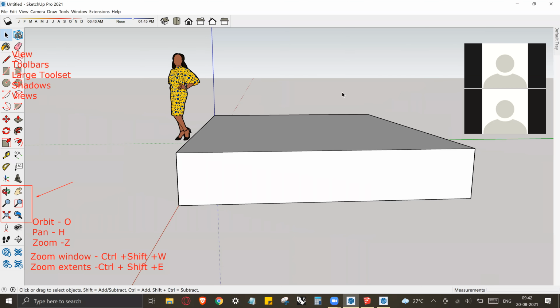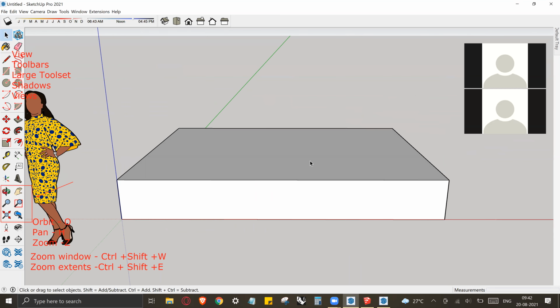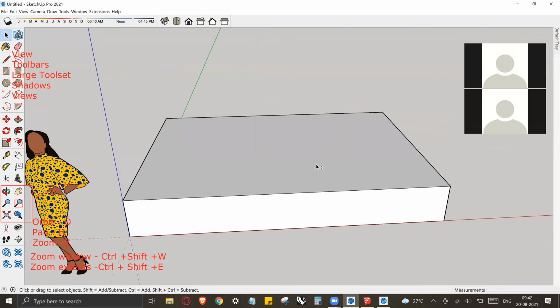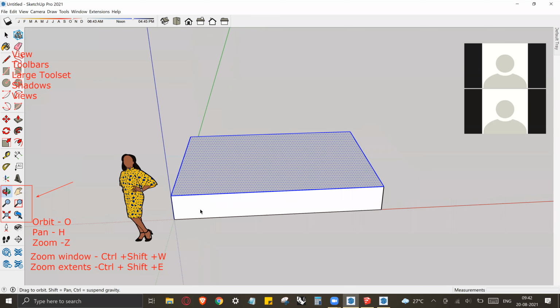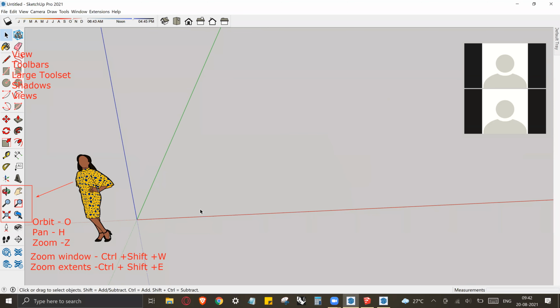And now, guys, let's see how you can go create this entire thing here. All right. You see, basically, it was just a rectangle at this point, right? Now, guys, the shortcut for the rectangle tool is just the letter R. You can go just click on R for now. And then you see you have the rectangle tool. Now, guys, when you click on this point here, you just drag it out. It is showing you a preview of how the rectangle will look. And now you can just click a second point. You see it has made a surface.